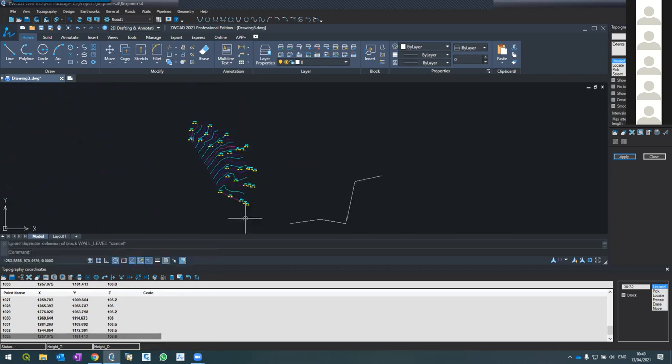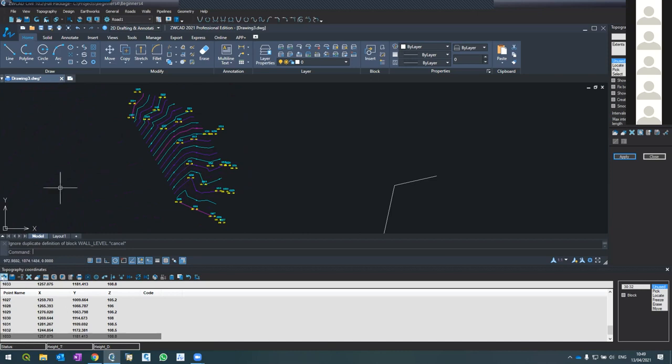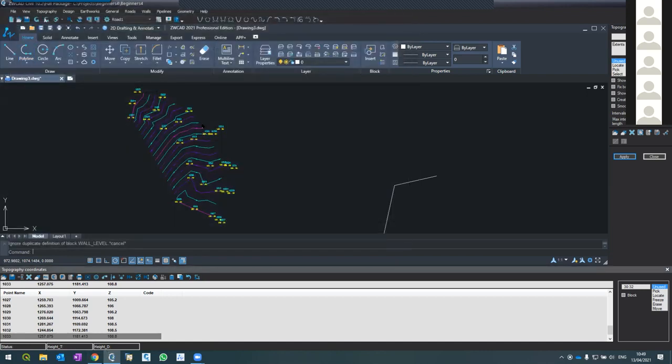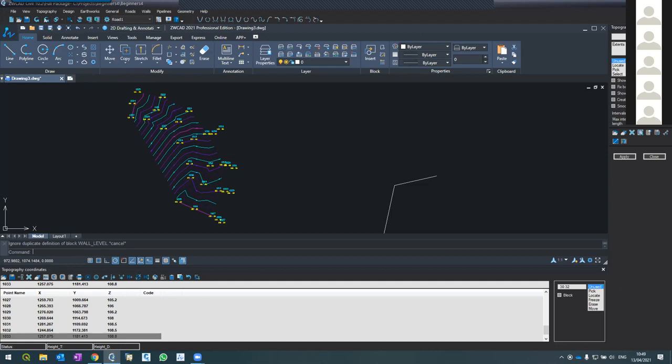So this is what I did. I'm a surveyor and I surveyed 2 more points on the top of the cliff. I finished with my road. Then I climbed up, and this is only 5 meters, it's not that high. And I surveyed 2 points here and continued 2 points here, 2 points here, and 2 points here. And I came from the field, I loaded, like open it from here, like we did for sample 7, load the coordinates, press refresh. So the coordinates, I'm okay. I'm going to topography contours like you did. And enter 0.25 and press apply. Let's see what will happen.